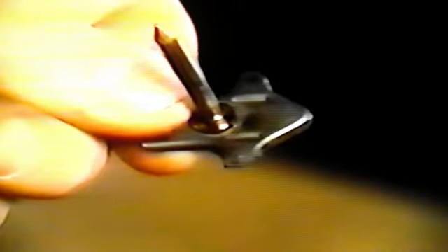The next thing to look for is pitting on the underside of the paddle arms. On high mileage carbs, this can become a serious problem. A badly pitted arm, one with a small hole worn in it, can cause uneven travel of the metering rod and incorrect fuel delivery. If you discover signs of pitting, the complete mixture control solenoid should be replaced.